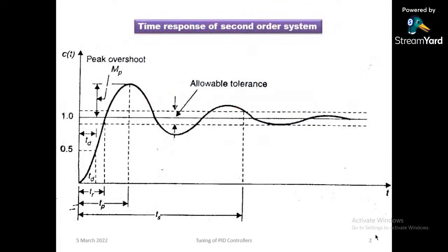Based on that, we also studied the standard second order system, and the parameter called damping ratio, that is zeta. Zeta is nothing but the tendency of the system itself to oppose the oscillation. You can make a note of that. In certain systems, this tendency may be very high, in certain systems it may be very low, or it may be moderate by nature.